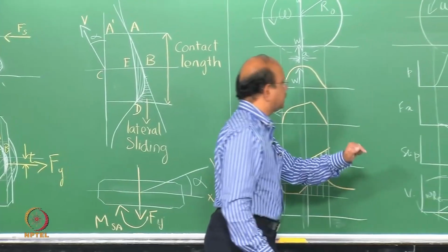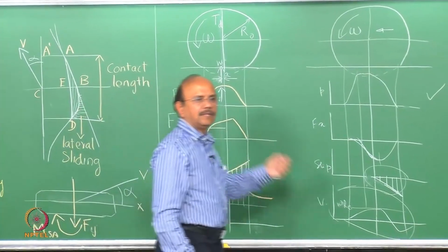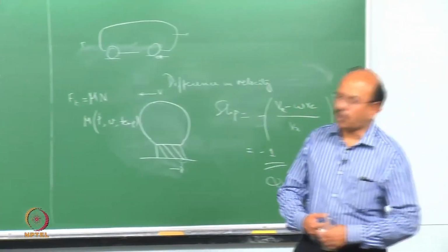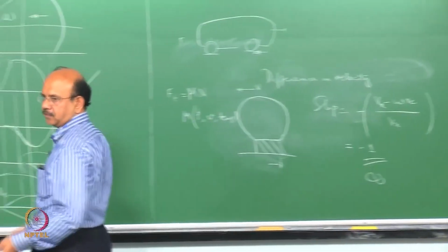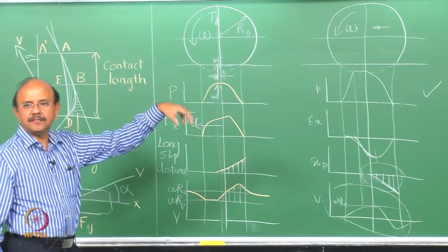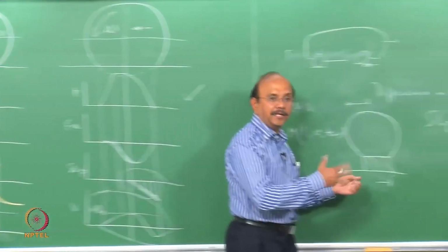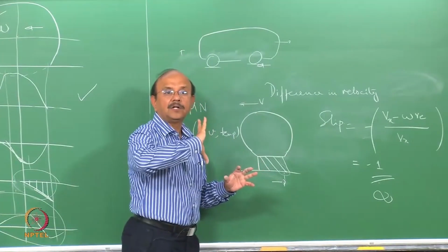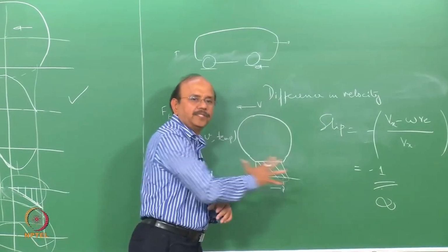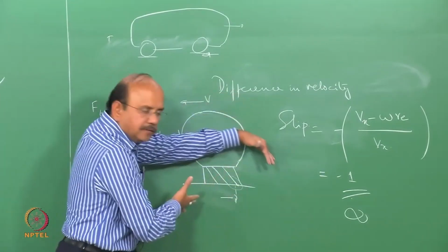Now, what happens is exactly similar in the case of acceleration or traction conditions. People call this traction whenever there is an acceleration. Now, the scene is just the other way. You are accelerating, that means you have given the acceleration, a torque is generated, and the torque rotates the tire faster than what the ground is moving, and hence this whole thing is the other way.